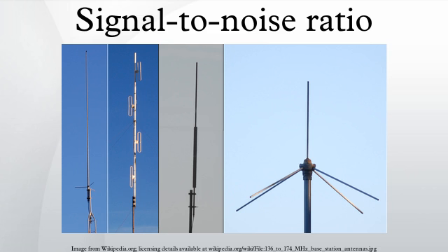It is often possible to reduce the noise by controlling the environment. Otherwise, when the characteristics of the noise are known and are different from the signals, it is possible to filter it or to process the signal. For example, it is sometimes possible to use a lock-in amplifier to modulate and confine the signal within a very narrow bandwidth and then filter the detected signal to the narrow band where it resides, thereby eliminating most of the